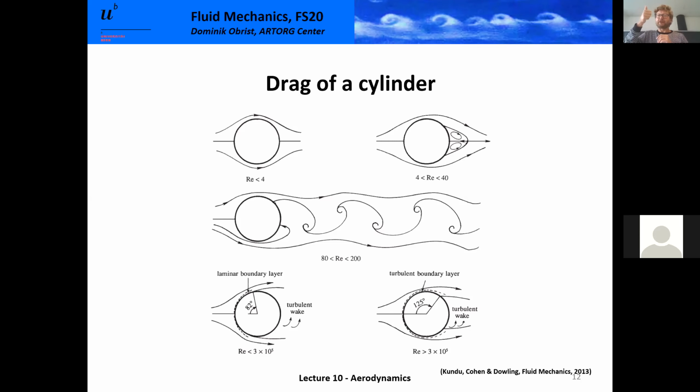which increased the friction drag, but we reduced the size of the wake, which reduced the pressure drag. Which one is stronger? Well, because this flow configuration in the first place is a pressure drag dominated configuration, the reduction of the pressure drag counts more.